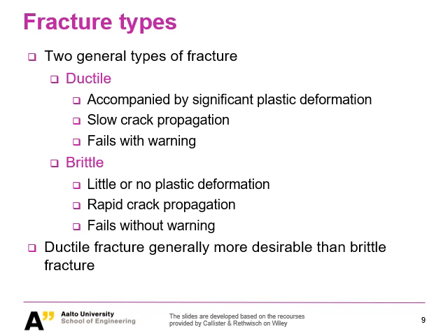All right, now let's get a basic summary about these two fracture types, ductile and brittle. I'm giving you 3 characteristics for each fracture type. First, let's talk about ductile. The first feature you probably have already noticed is ductile fracture is accompanied by significant plastic deformation. We have seen this from the stress strain curve for ductile fracture, which is of such a type. And you also see it from the fractured pipes with a significant amount of plastic deformation.